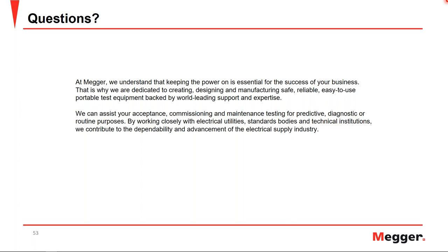So there are different variations of power factor testing. And if you are talking in general about insulation assessment, there are other tests available like DC insulation, PD, high pot. On cables, you do VLF testing. There are just a number of other tests available that can be used for insulation assessment.